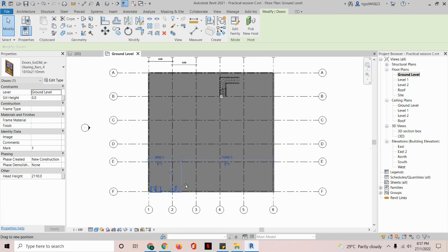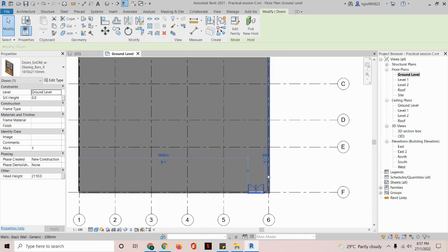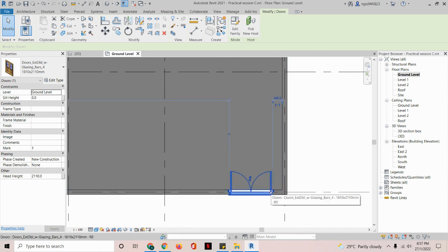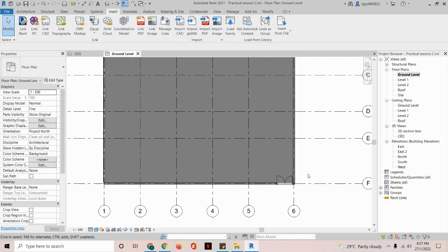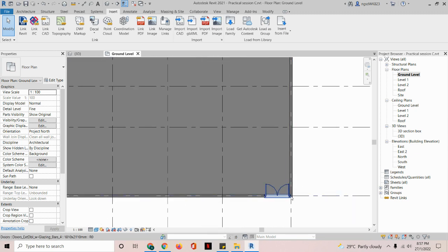Okay, so let's say for example, I don't want my door to be next to the curtain wall because that is more of an exposed feature. So I move it over to the right side, and then I ensure that I have around 400. Having the door next to this wall is okay, which is something like this. If it's zero, it's still okay. But this depends on the design. If you really want to save the space, having the door straight next to this is alright, as long as this door can be opened and closed properly.